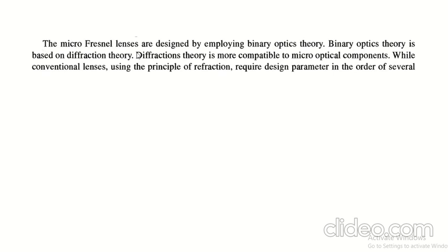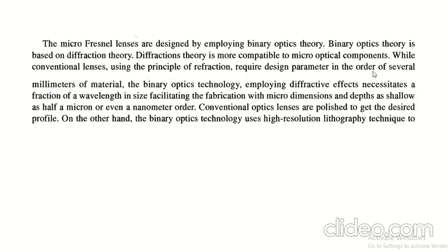Micro Fresnel lenses are designed by employing binary optics theory. Now, binary optics theory is based on diffraction theory. But diffraction theory is more compatible to micro-optical components, while conventional lenses use the principle of refraction, and require design parameters in the order of several millimeters of material.